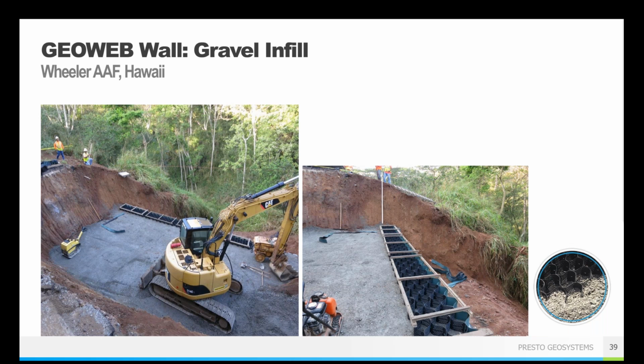So you're not looking at using large riprap style boulders. You are looking at using a good, clean aggregate gradation. And it is important to limit the fines content of your aggregate when you have drainage concerns like this. And when I say limit, I'm thinking 10% or less fines in your material.